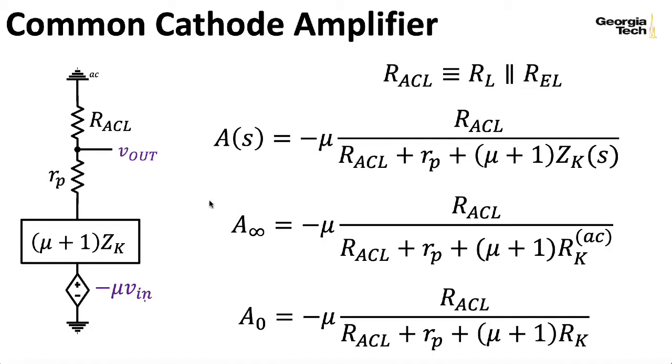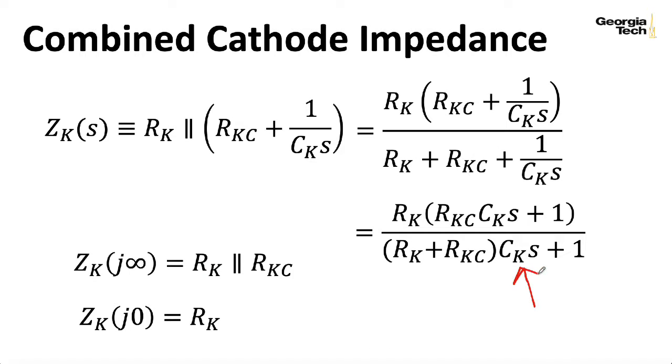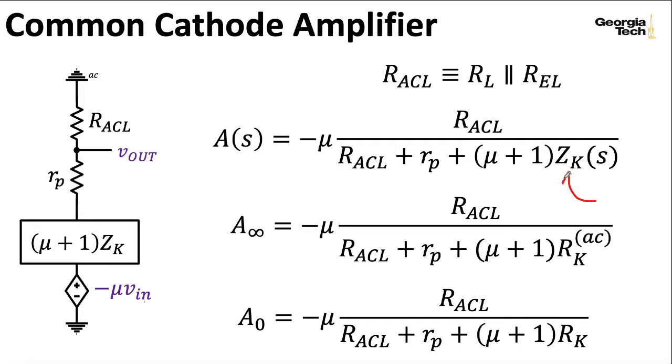We know that the full circuit is going to have a coupling capacitor that's going to block DC, and we know that we'll never be able to pass super high frequencies in a realistic system because eventually parasitic capacitances would eat your lunch, although usually that's not too big of a deal as far as audio frequencies go. We'll look at this issue a little bit later. We're going to use this expression here to try to derive some expressions later that are easier to interpret in terms of time constants.